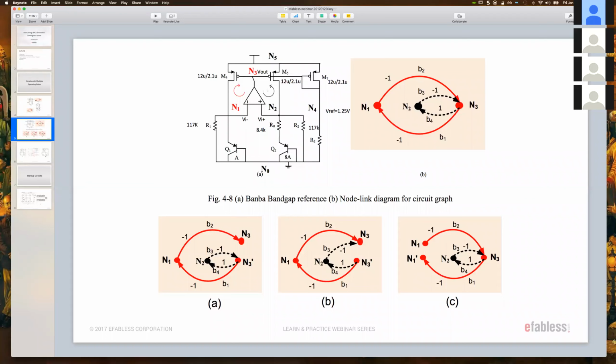Back to something like this, there is another example that used a different approach, where multiple loops were used, where you're using a high gain stage to control the accuracy of the voltages across the mirror and the transistors here. So you will have multiple loops: a loop here and a loop here.